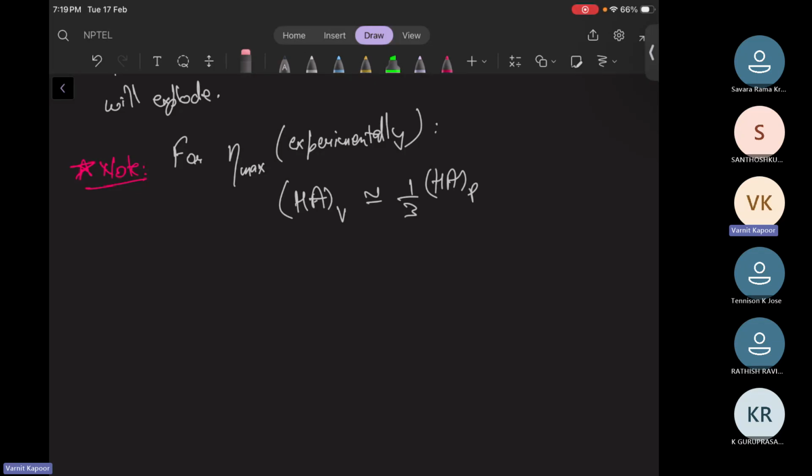Now the piston is moving, because the acceleration direction has been changed. Although velocity is zero, the acceleration direction has changed because of the presence of inertia, and we have a flywheel. As soon as the direction of the acceleration changes, the piston still goes downwards, and the fuel supply has not stopped. Fuel will still be supplied from that position, and the pressure is maintained constant, and that's why we say the heat is then added at constant pressure. Everything in detail I have explained in my previous tutorials, you should go back and check. Okay, is it clear?